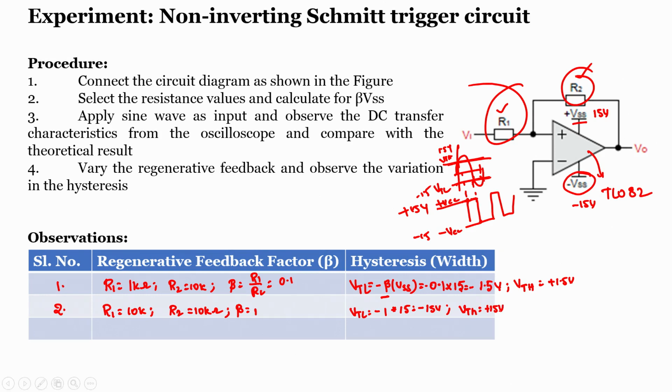But in a simulation we can easily see this, because there are no restrictions on the input voltage. This is very difficult to visualize experimentally, because with our source, the maximum peak to peak value you can get is 20 volts. That means the peak value will be only 10 volts. Since in this case we require a peak of more than 10 volts, this cannot be used in our application. But in simulation we will see how exactly it works, whether it is working as expected or not.